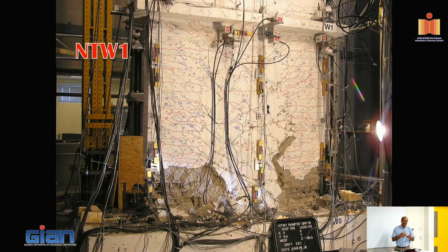We are coming up with this detailed stuff. Typically in Japan and the US, the use of couplers has become very frequent. It became cheaper, and I think it's probably the same here. The cost is not an issue, so people tend to use couplers. It's not a bad thing, but it changes the behavior. That's something you should recognize in your analysis as well.